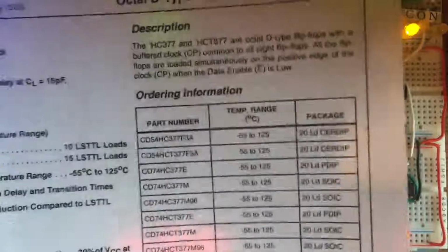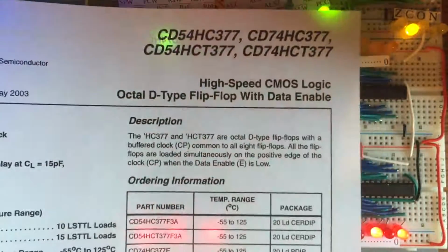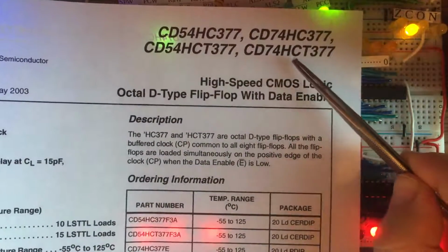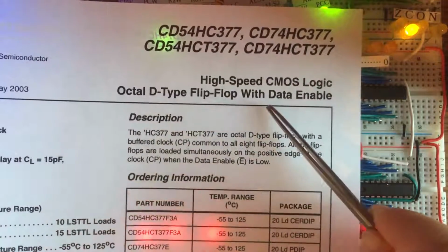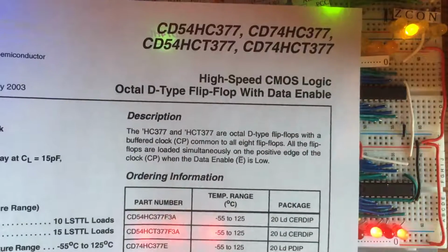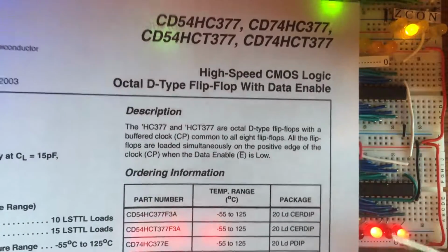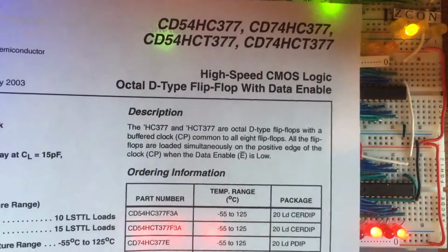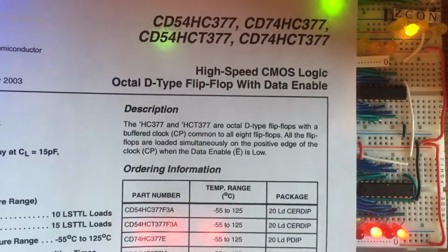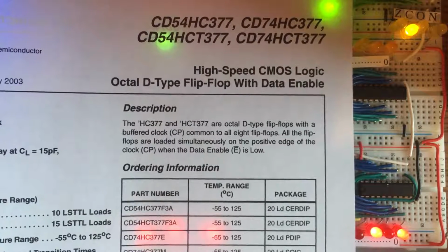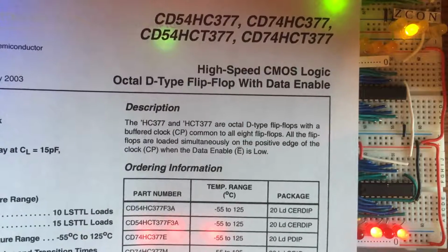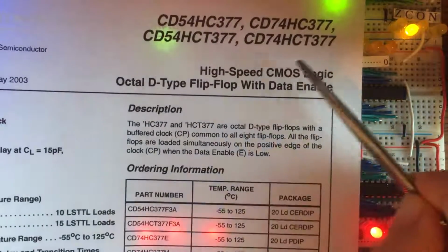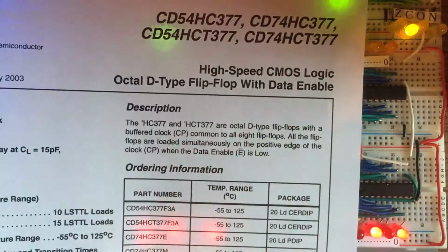So here is the datasheet for that chip. We're using the 74HCT377. And so that's a D-type flip-flop, which has an enable signal. And the big advantage is that it's 8 bits large. If you remember from Ben's video, he actually needs 2 chips for each register, because he's using a 74HCT173, and that is a D-type flip-flop which can only store 4 bits. And so this 377 is a little bit bigger, and it can actually store 8 bits, which is what we want for a single register.